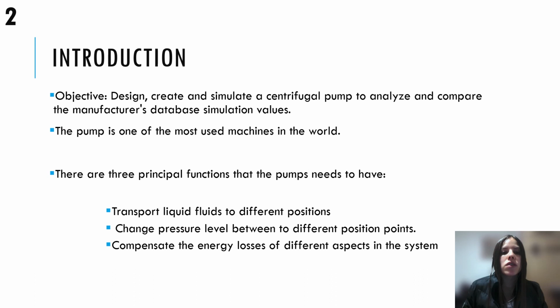The pump is one of the most used machines in the world, and there are three principal functions that the pump needs to have: transport liquid fluids to different positions, change pressure level between two different precision points, and compensate the energy losses of different aspects in the system.